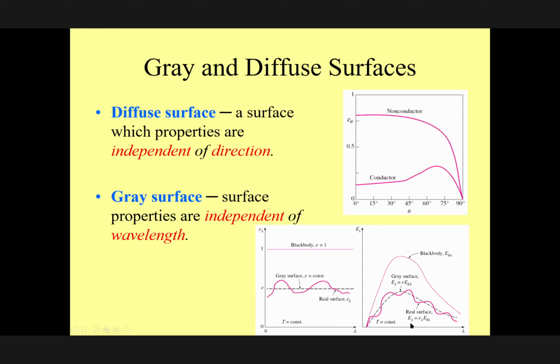Look at this material again. This is the black body. We assume it behaves like this, but in reality, the emissivity coming from the material changes like this. It is a function of temperature. Therefore, the number that you have in the table is an average for the given application that we have.